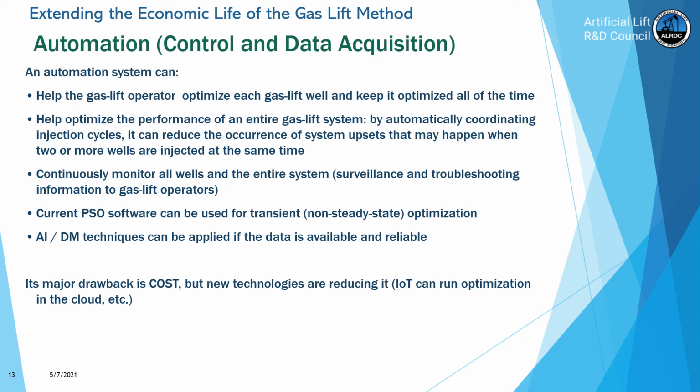So once the pressure increases to the opening pressure of the valve, the intermittent can close. In that way, most of the gas that is injected into the tubing is already in the annulus. So the high pressure side of the system doesn't see anything, and we can have wells that are intermittent on their own. We don't really care if too many intermittents are opening at the same time.